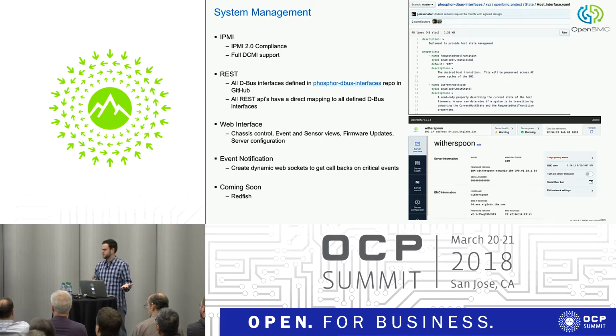Well, we found this really cool REST server that you could put on top of dbus and would basically just export all of those as REST APIs. And so really, that was and is currently the main mechanism for managing the OpenBMC systems. The cool part is you can do anything through this interface. The not so cool part is, it's just dbus interfaces, so if you want to change something internally, you start breaking your external REST APIs, which we've had a few vocal people in the community let us know of when we've done that. And the other problem is, this isn't a standard, right?